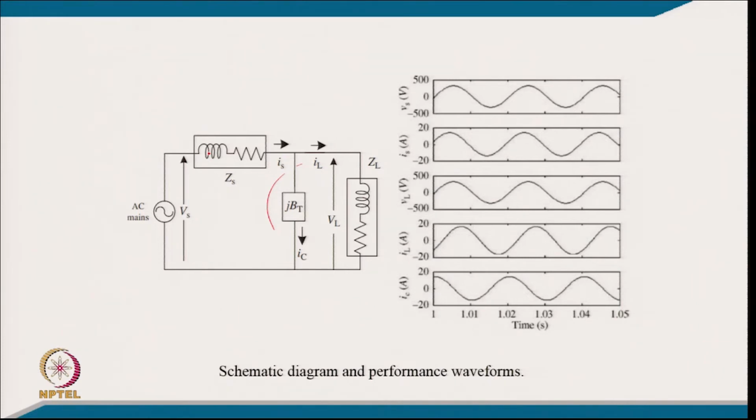Well, of course, you can see here, we put the values and made this waveform for these actual data, and you can see this current, I mean the source current, is slightly leading the voltage. So, even for 0 voltage regulation, meaning whatever is the source voltage should be equal to the load voltage, there will always be a little leading power factor, because your source impedance is of inductive nature, and that is the reason you can see all the parameters here. However, the compensator is capacitive, so this current is typically 90 degrees leading the voltage. The load is certainly inductive, so it is lagging the voltage. So, all these waveforms can give you the concept of how this compensator will work.